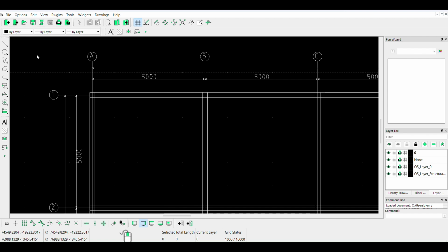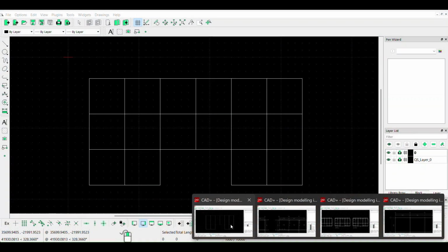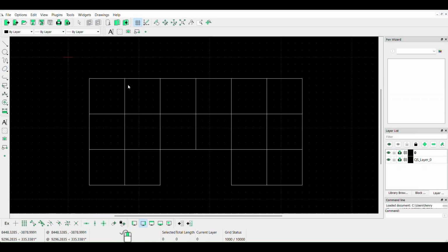so it's okay. But if you have so many lines, like here, looking at this beam line and all the rest, and of course I'm just using a simpler architect floor model. I know when you get a drawing in AutoCAD from an architect, sometimes it's very complicated, and there's quite a lot of lines everywhere. That's one of the reasons why, to prepare it for use within the software, it's always better to strip everything off and bring things down to only the rectangles or the polygons that you need.